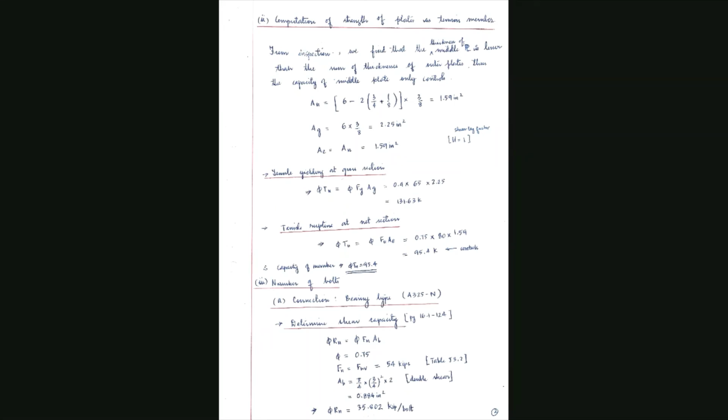Actually, it's double shear. When I say double shear, what do we mean? If you have a bolt right here, it is subjected to two planes of shear.